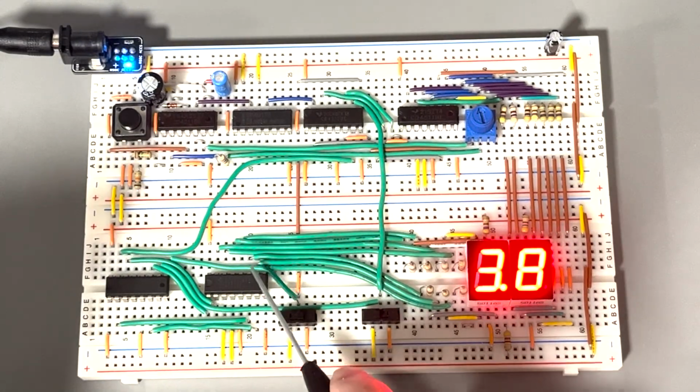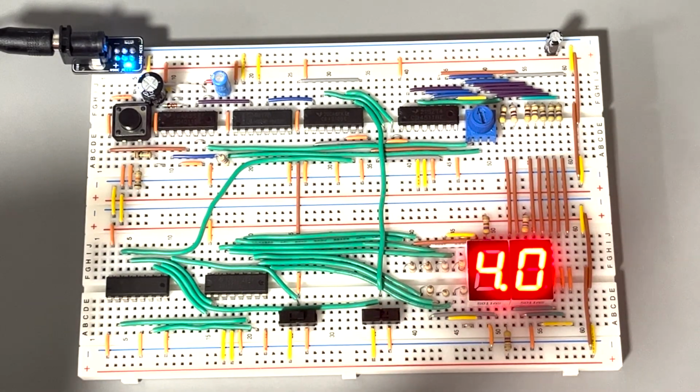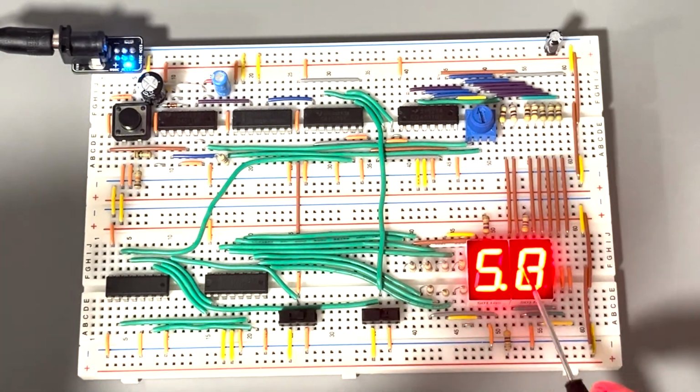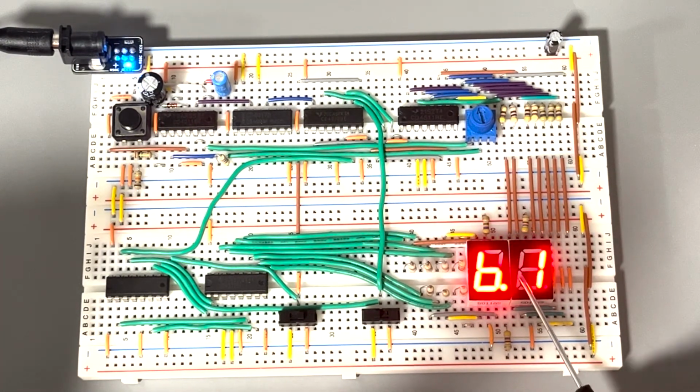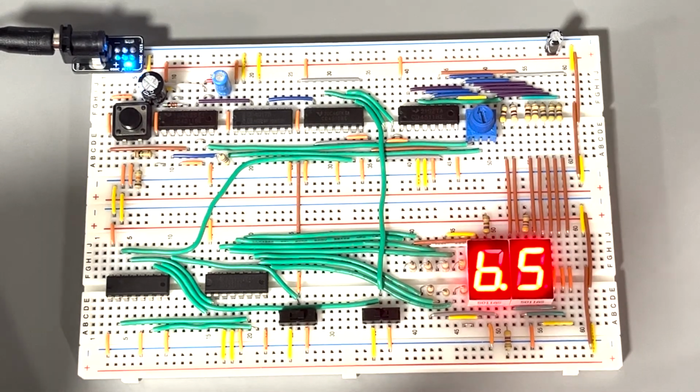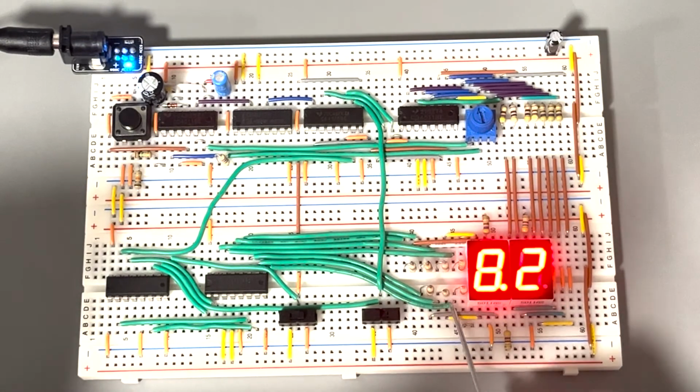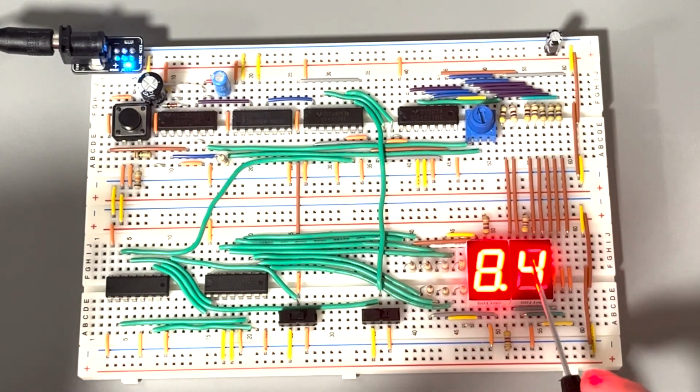In order to achieve this, it uses many different arrangements of different logic ICs. The 7-segment displays count the clock signal in decimal form. I use resistors to drive the two displays as there is no built-in resistance within them.